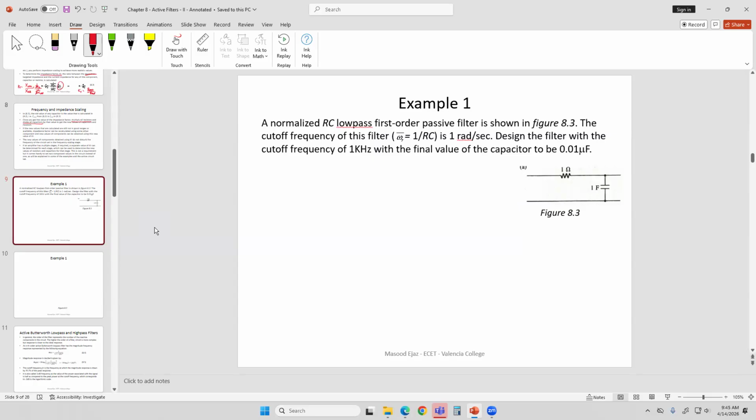So when you have low frequencies, start with DC, omega is 0, and the reactance of the capacitor is infinity, 1 over 0, very high. That means it's going to be an open circuit, so whatever input is coming in is going out. No current flows through the circuit, no drop in the resistor. As omega increases, reactance goes down, 1 over omega c. When omega becomes extremely large, reactance becomes extremely small. Let's say omega becomes infinity, reactance becomes what? Short. So the output becomes 0 because it's parallel to the short circuit.